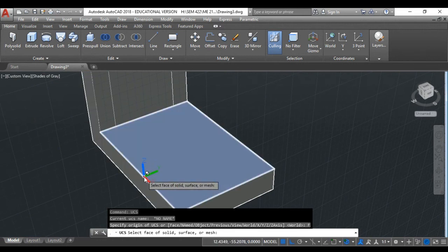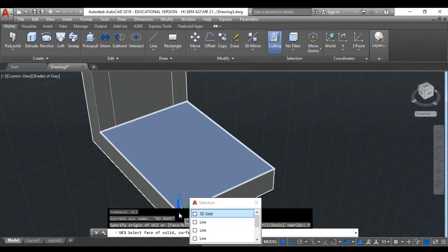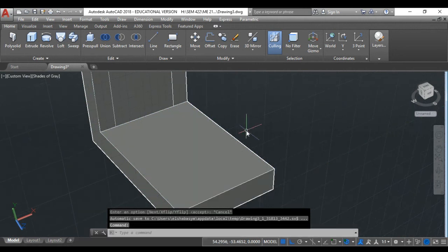You can select the midpoint of that, but be careful guys before you make your click, because if I come to the border you will notice that I might activate a wrong plane or a wrong face. So be careful, before you make your final decision, to see that the one that you are intending to draw on is the active one. Clear guys? So I'm gonna come closer to that edge and then I'll be happy to put my surface like this. 3D solid. Okay, I'm sorry.